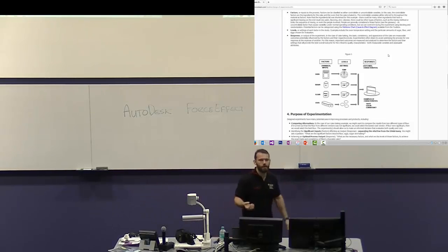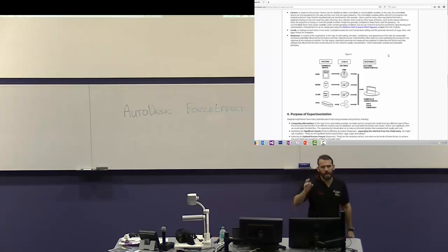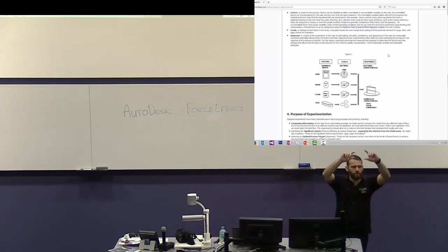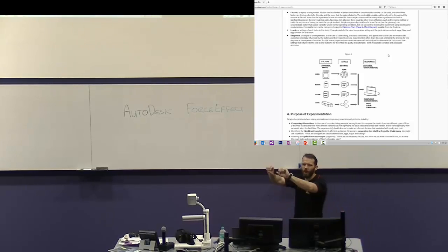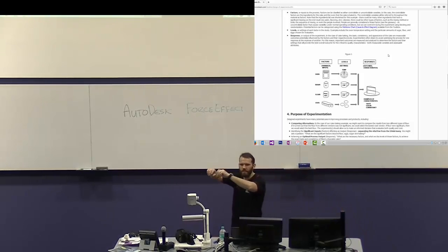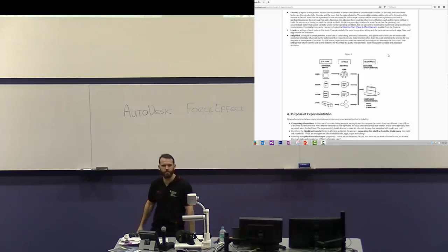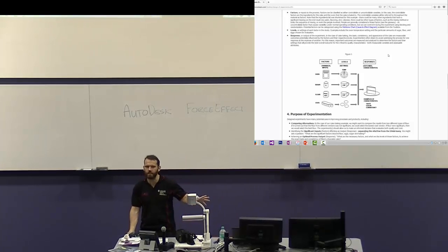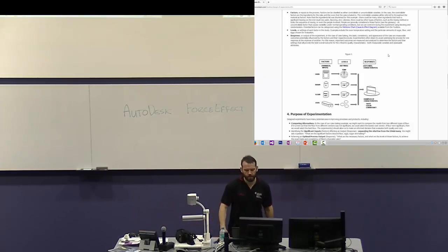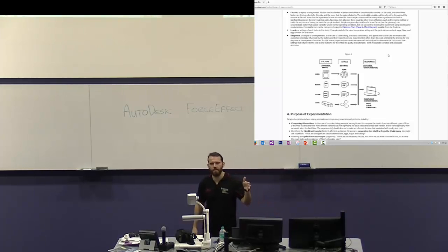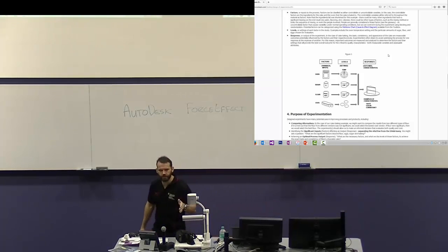What about shape? Because a square cross-section and an I-beam cross-section are not equal in the way that they carry loads. Particularly, I-beams are good for bending. They're much, much better. You use far less material to carry the same amount of bending. We've got less bending in this situation. You guys haven't really learnt about bending yet. But there are different configurations that you can have there. All right, so those are the factors, and then what you're going to work out is the levels.